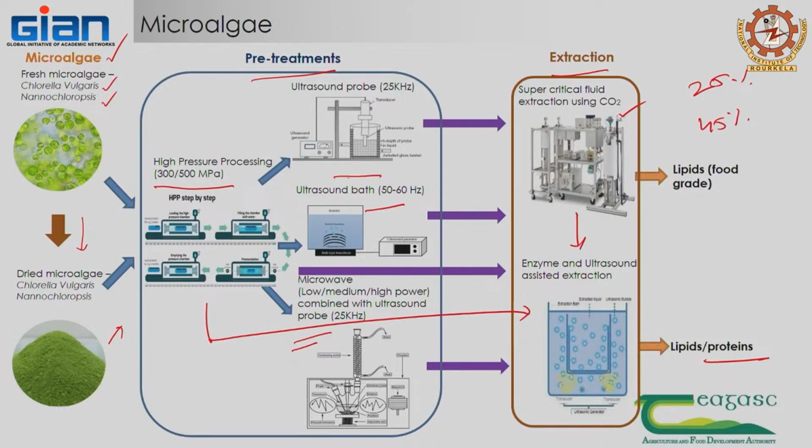So if you just have a simple stuff of using Viscozyme, have you heard of Viscozyme? Viscozyme is a commercial name from Novozymes, that is carbohydrases, which is a mixture of cellulase and all other carbohydrases, which can break that carbohydrate and then leave the protein, and carbohydrates are broken down into sugar. So a simple membrane system can remove the protein from sugar suspension to concentrate the protein.